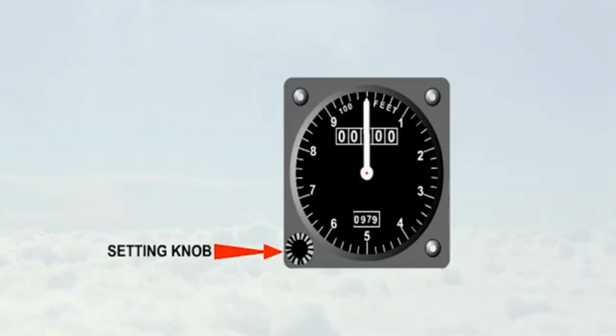The simple altimeter can have a setting knob which is geared to the pointer. With this knob, the pointer may be set to read 0 with the aircraft on the ground, so that when airborne, the altimeter indicates the approximate height above aerodrome elevation. Alternatively, the pointer can be set, before flight, to the aerodrome elevation, so that when airborne the instrument shows approximate height above mean sea level.